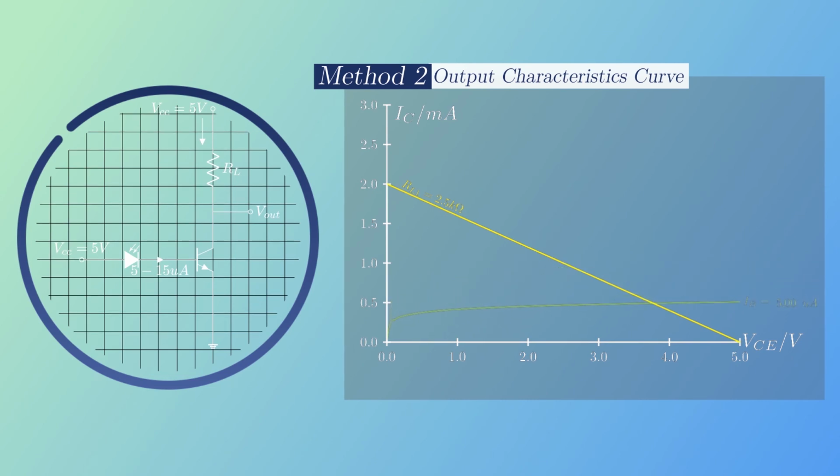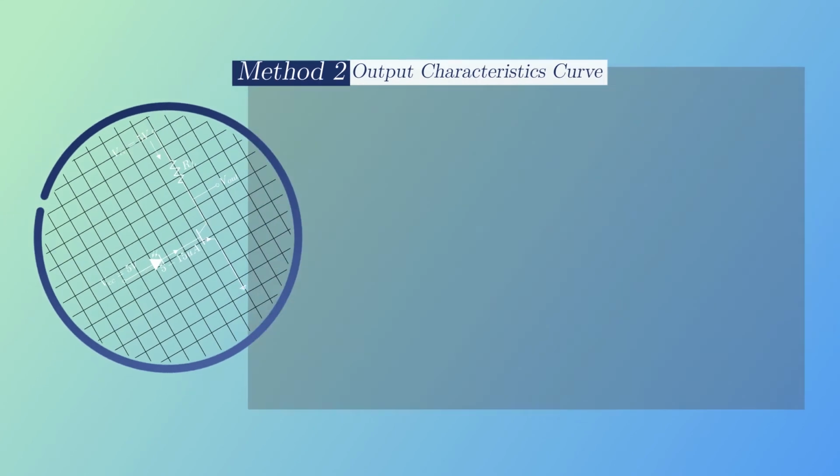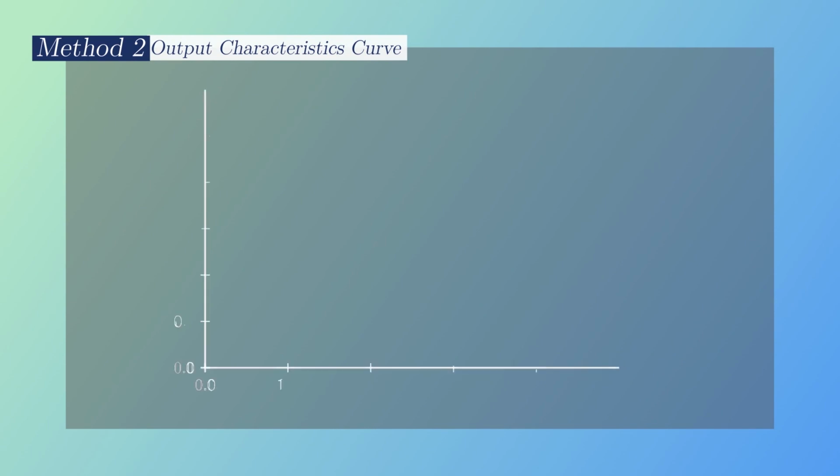With that being said, let's take this idea a little bit further and look at its response under the same base current exposure with a 5 kilo ohms resistor. A quick sweep across the range reveals just how changing a resistor value can alter the response of the whole system, mapping the base current into a new set of output voltages. To spice things up a little bit, I'm going to track how Vout changes with time when both of these resistors are being exposed to the same sinusoidal base current input, drawing out their paths as they wiggle through time.